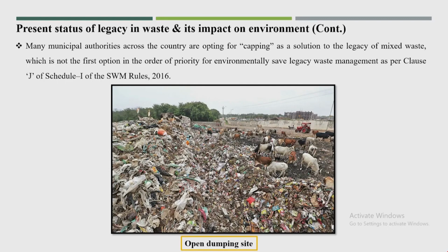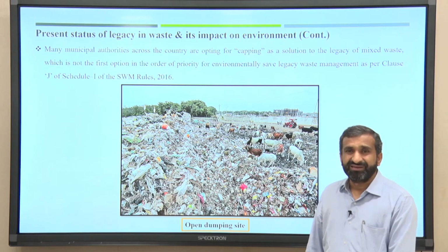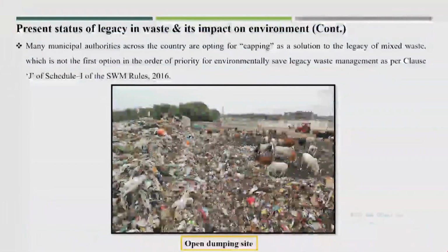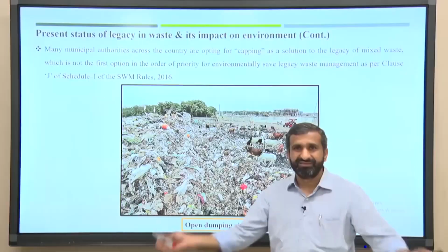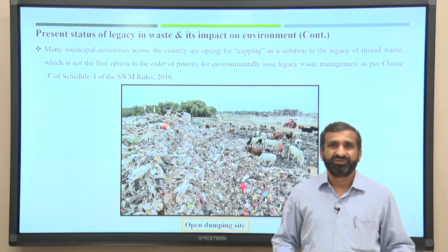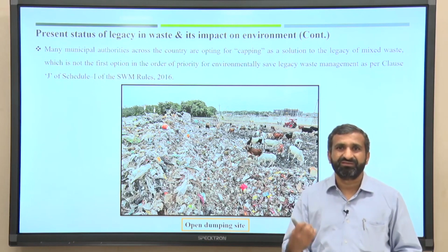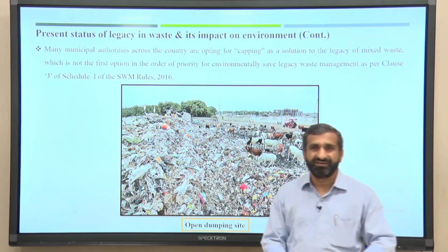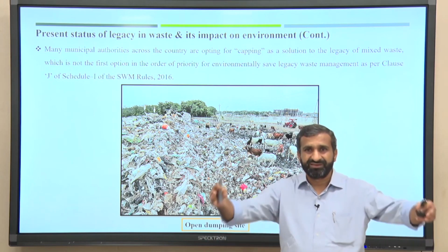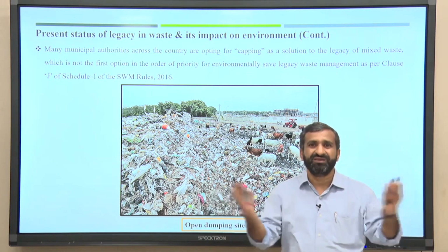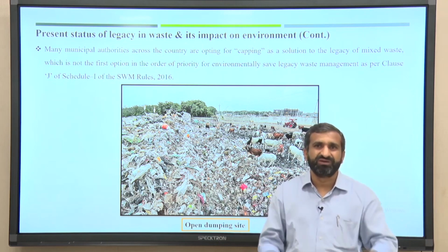Many municipal authorities across the country are opting for capping as a solution for legacy mixed waste. Some cities understood capping as closing the entire area and filling soil on top. If you visit the dump sites in Surat, they capped the entire area completely and filled soil on top of the waste material.